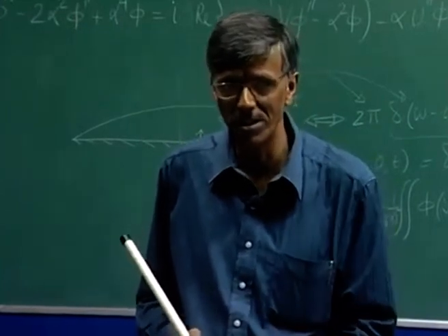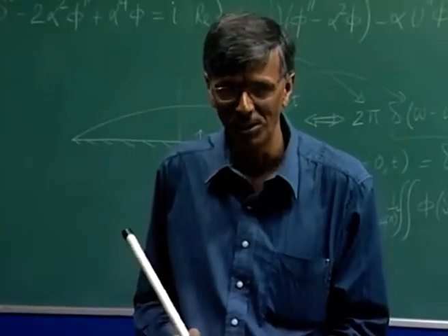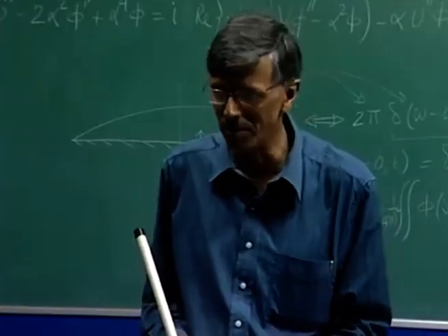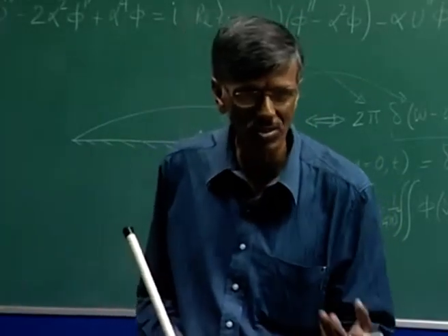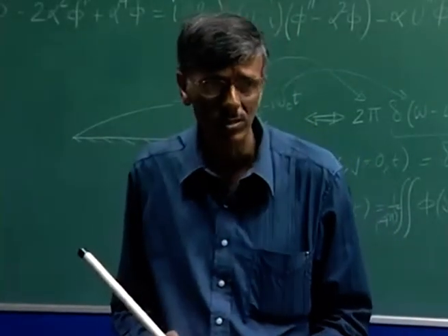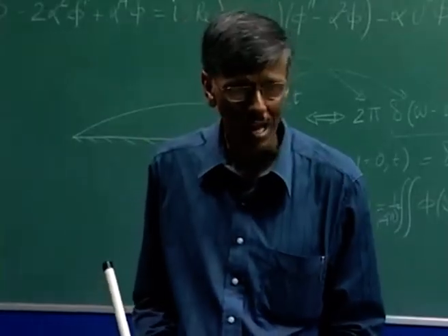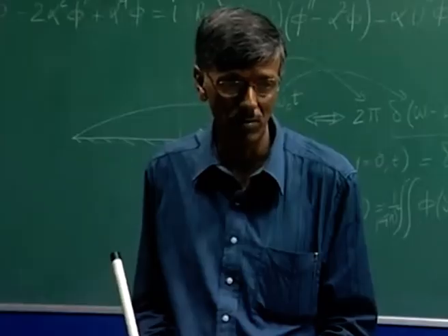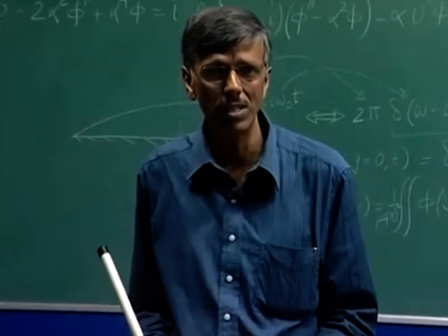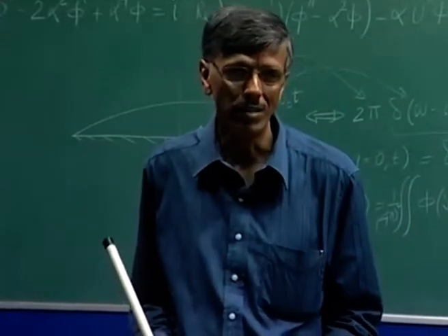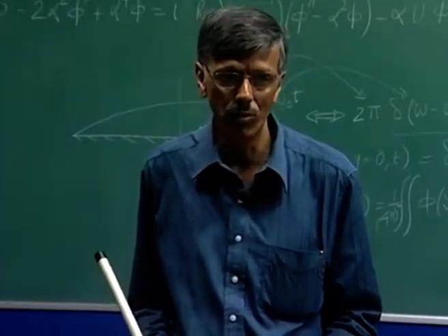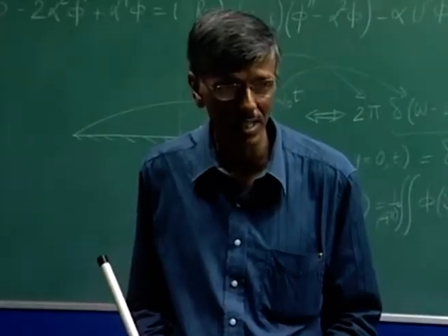And that was your question in the mid-sem. Reynolds experiment relates to, is it a question of nonlinearity or is it a question of receptivity? To me, it appears it is a question of receptivity. If I can stop the background of that particular class of disturbance where the dispersion relation resides, I will not have that response. And that is why people have gone ahead and obtained Re critical for flow past a cylinder to a very, very large value. That has gone as close to as 100,000, while Reynolds obtained it around 12,830.